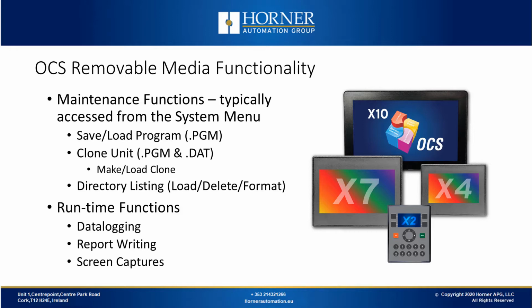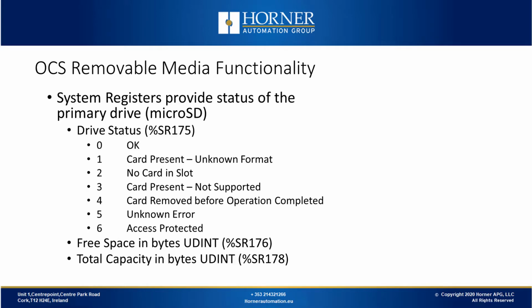Media functions can be useful for maintenance. You can save or load a program, you can clone your unit without losing any password or intellectual property protection, and you can view the directory on the memory card. At runtime, you can log data, write reports, and get screen captures. There are a series of system registers that can provide status of the primary drive, which is usually the microSD drive. There are 7 different status codes for the drive, which are currently on screen. There's a system register which gives you the free space available in the drive. There's another system register for the total capacity of the drive.